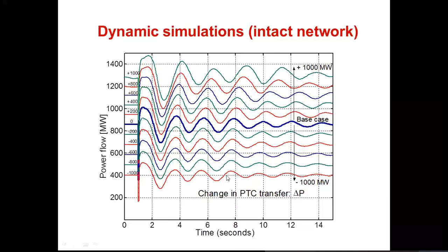After 8 seconds, the response gets damped out. But if you have an increased amount of power flow, even after 8 seconds, an oscillation is still being observed. So it is very important how much loading you apply on the line, such that the oscillations remain minimum.